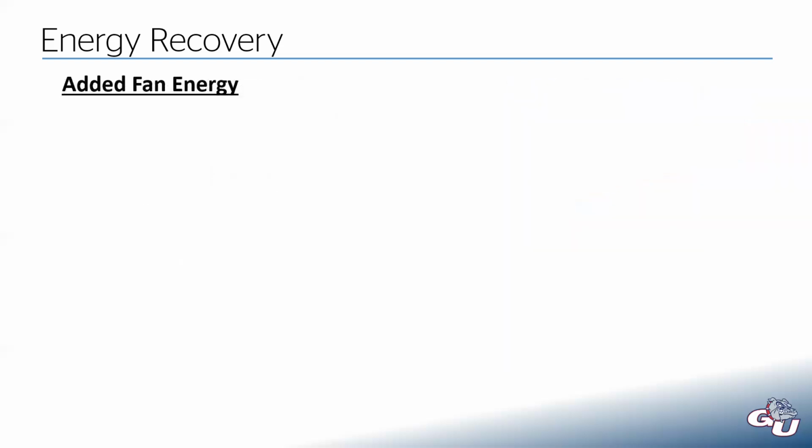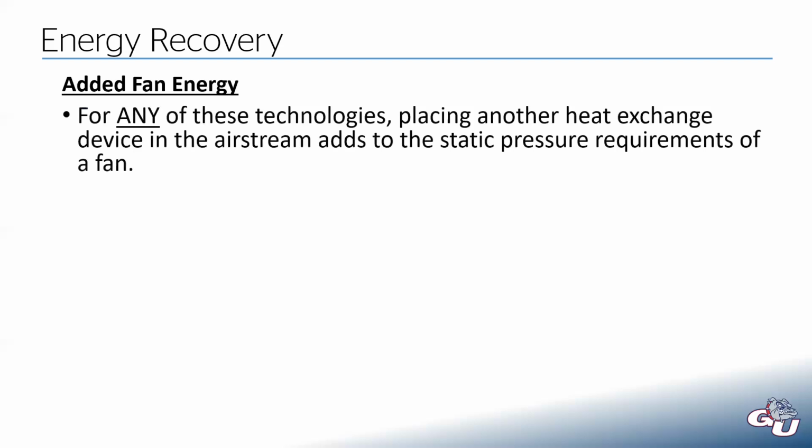So with energy recovery, we're getting into interactive effects here. For any of these technologies, we're placing another heat exchange device in our airstream. And anytime we put something in the path of the airstream, we are adding static pressure requirements.